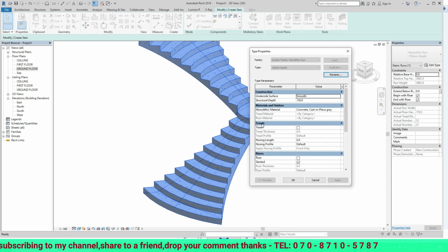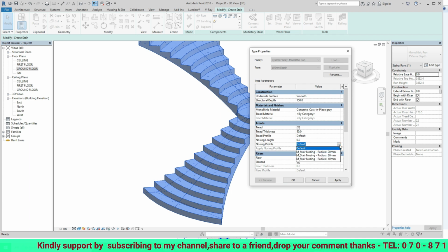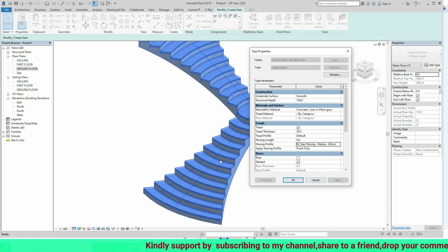Under edit type, you see tread. Click on the tread profile, nosing profile. You choose the style of nosing you want to use. Let's use stair nosing radius 20 mm. Click apply. Have you seen? Look at it now.